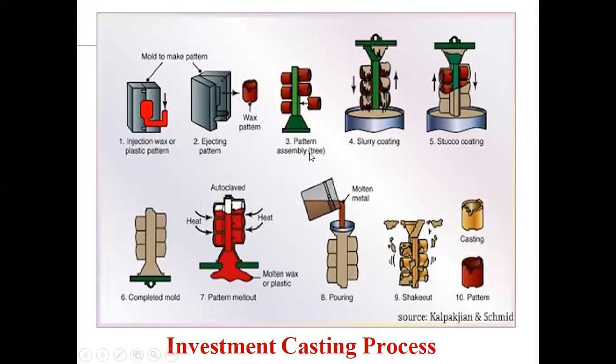Now pattern assembly or tree. So you will make a kind of a tree, right? Now you'll dip it in a slurry, up and down, you see, dip it again and again so it achieves a certain thickness. Stucco coating. We'll see what this coating consists of. And then you see the completed mold after repeated dipping into the slurry. Now, because these were made of wax, you remember, once it is dipped and the wax patterns are inside, if you apply heat, that wax pattern will come out, isn't it?